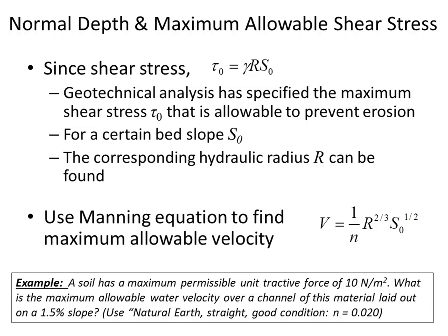There are some things that a hydraulic designer can change, and other things that a hydraulic designer can't change. So let's say that you have a stream coming down out of the mountains, and it's going between 2 points. There's some elevation difference, delta Z, between the 2 points. And if the stream is just straight and it has some length L, we know that the slope is delta Z divided by the length of the stream L.